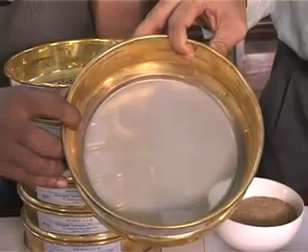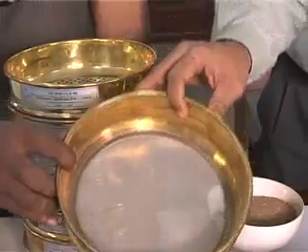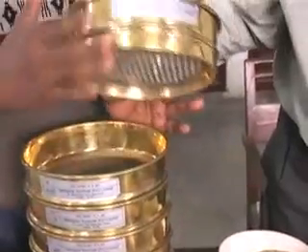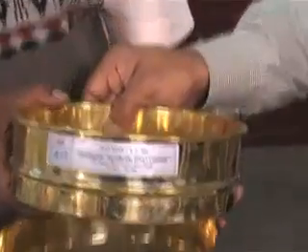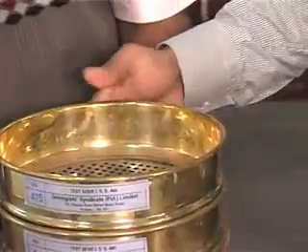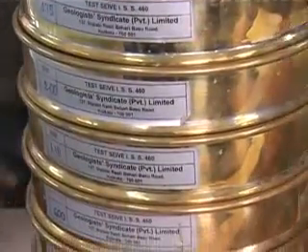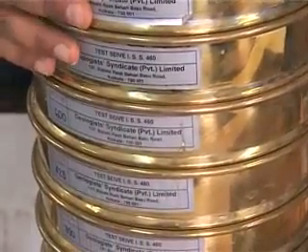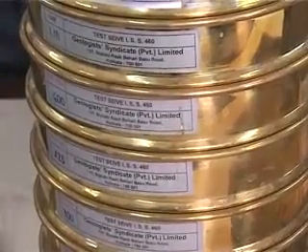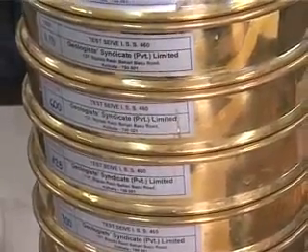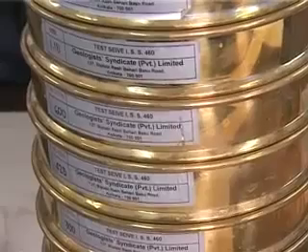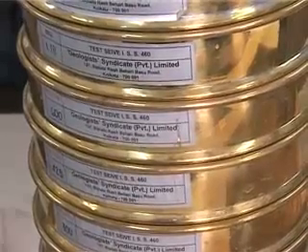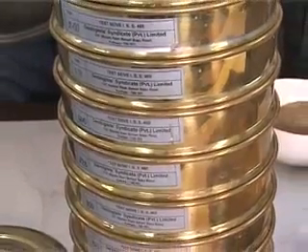This is the 75 micron opening size sieve, whereas the first one that you saw had an opening size of 4.75 millimeter, as is mentioned on the label. Now you can get the idea. Looking at the labels of the different standard sieves, you can see that they go down in size, starting from the top. The coarsest sieve is at the top and the finest sieve is at the bottom. Below the 75 micron sieve is a pan, which will collect all those particles which are finer than 75 micron.